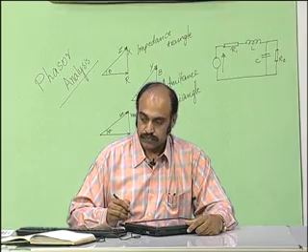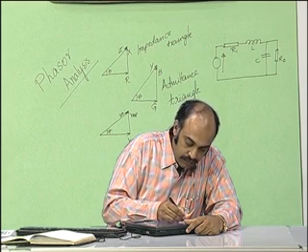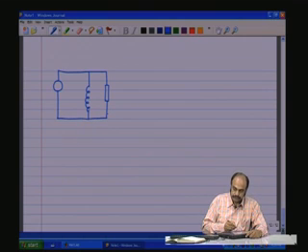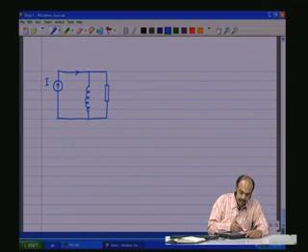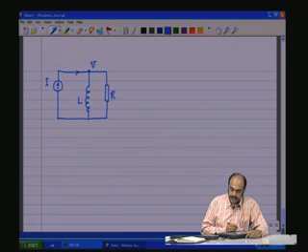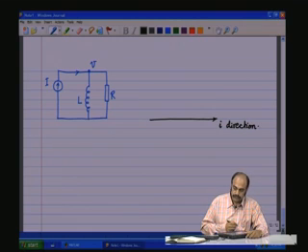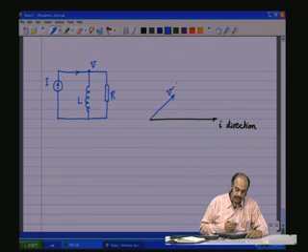Just one more issue. Let us take an inductive circuit, L in parallel with R. So, here this is a current source now, this is an I which is coming in here, this is an L and this is an R, there is a node voltage V. So, let us take the I direction as the reference direction, and the voltage, the current has to lag voltage or voltage has to lead the current, and therefore, you have voltage which leads I.